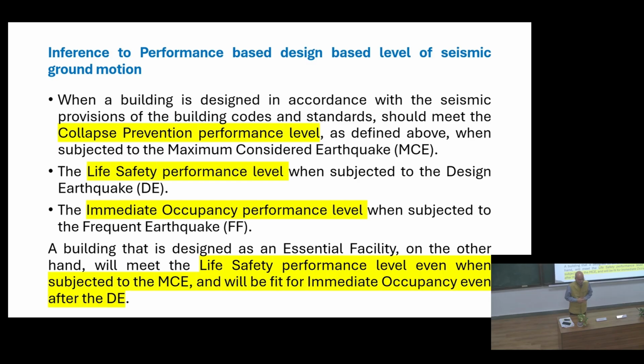What is the need of doing that? Because suppose a structure is designed for 50 years, 40 years, or 100 years. The loading which you have taken does not necessarily remain the same throughout those periods, because uncertainty is associated with it. To account for that uncertainty, this factor is included. So this factor does not come arbitrarily; some rigorous analysis has been done, and according to it the factor which is generated is given in the codal form.